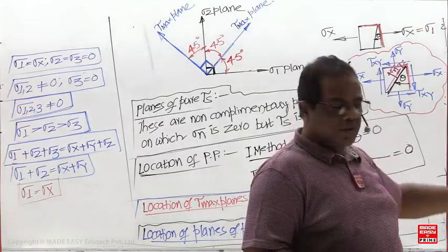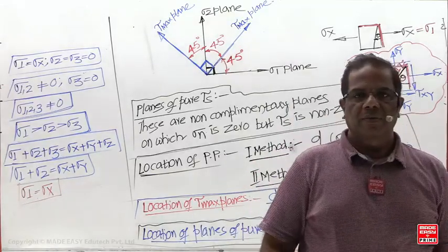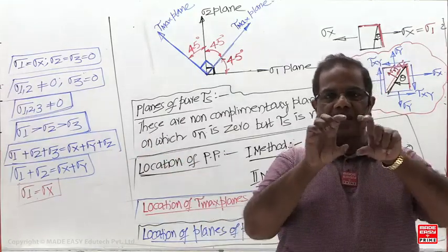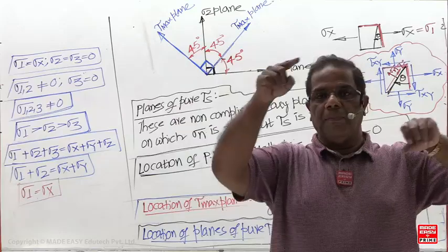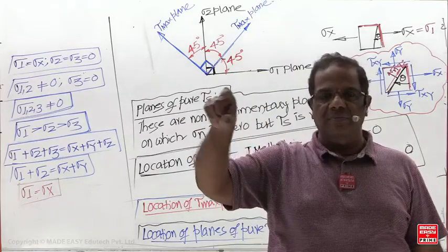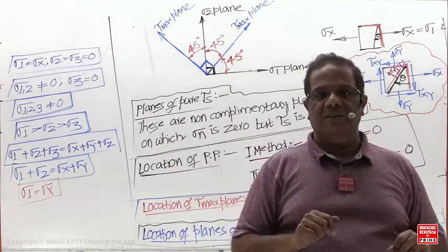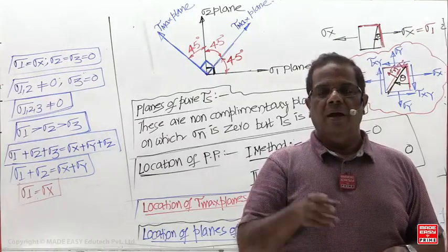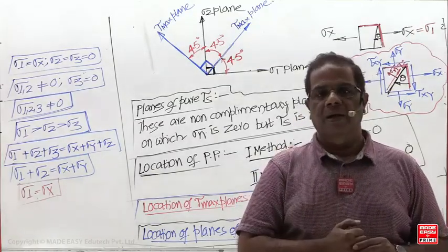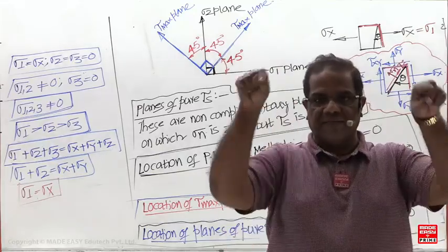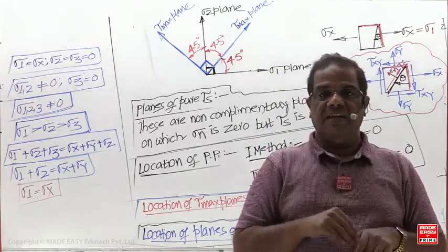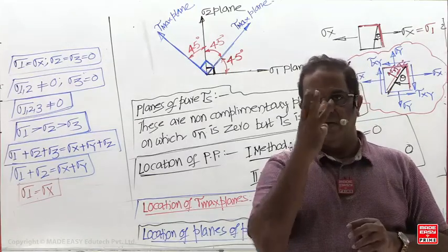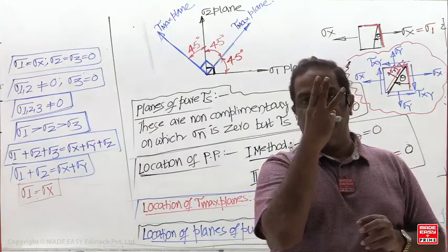After the break, I am going to discuss and show clearly the cup and cone fracture. Yesterday I drew the rough diagrams. I'm going to show the cup and cone fractures and the granular transverse fracture. Then I will show the difference between stress and pressure. Then we'll come to the state of stress. Clearly, I will mention what the state of stress is: a state of stress represents the stress on three planes.